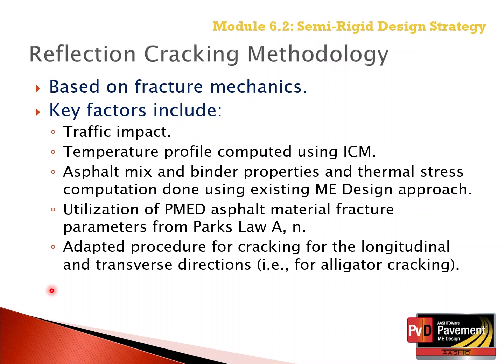The reflection cracking methodology is based on fracture mechanics. Key factors of that methodology include the impact of traffic from wheel loads, the temperature profile computed by the enhanced integrated climatic model embedded within the Pavement ME software, the asphalt mix and binder properties, and thermal stress computations done using the existing MEPDG design approach specifically for thermal fracture or transverse cracking.